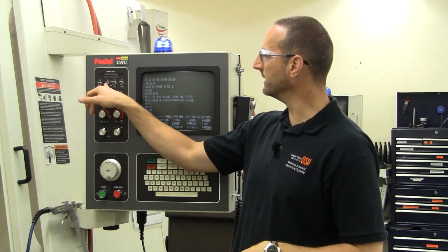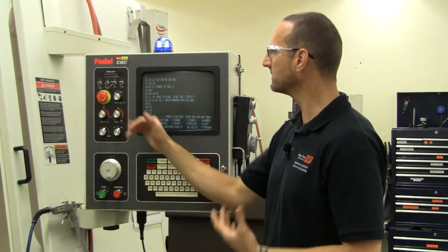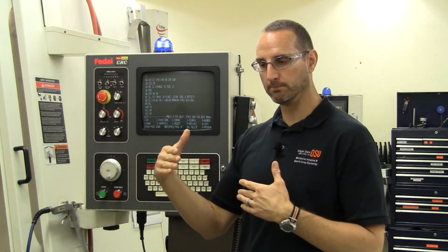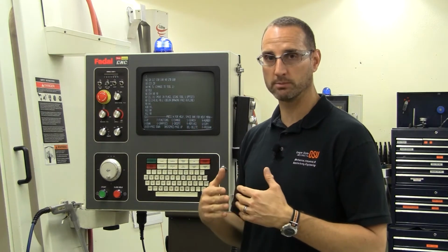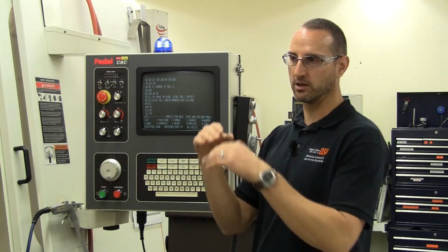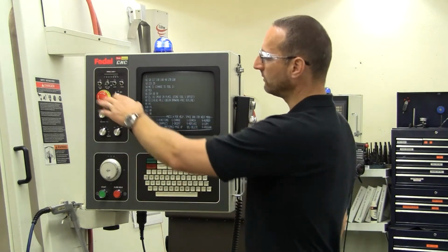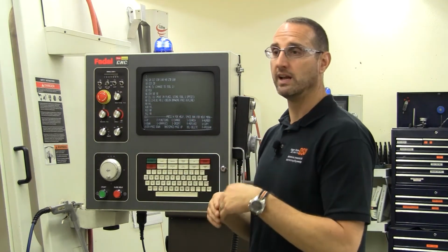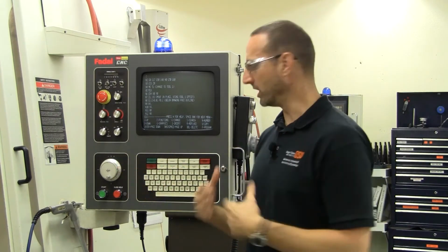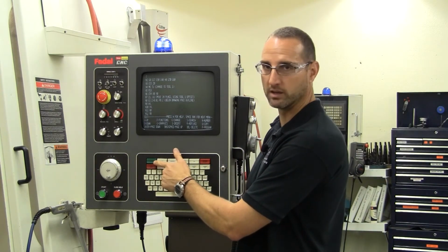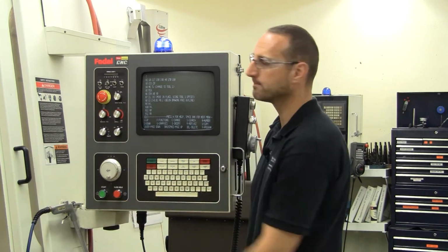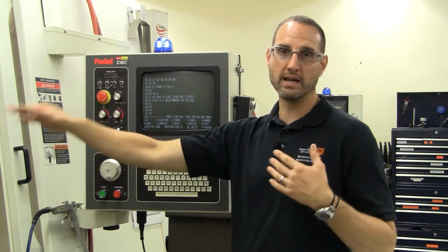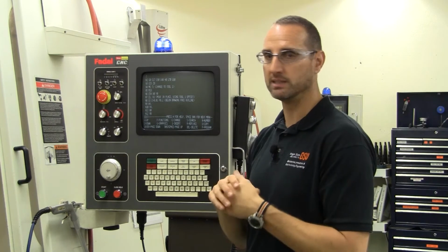Next to it is an optional stop. This is a similar type of controller switch. If in my program I have a code written that tells the machine to do an optional stop, the controller will come down to that line of code, read the optional stop command, and then check its position, whether the optional stop switch is on or off. If the switch is on, then the machine will pause and go into waiting mode and wait for me to acknowledge that I want to continue, either by hitting the start here or start there key. If the optional stop switch is in the off position, then it will blow right by that, ignore the optional stop, and continue to move on.